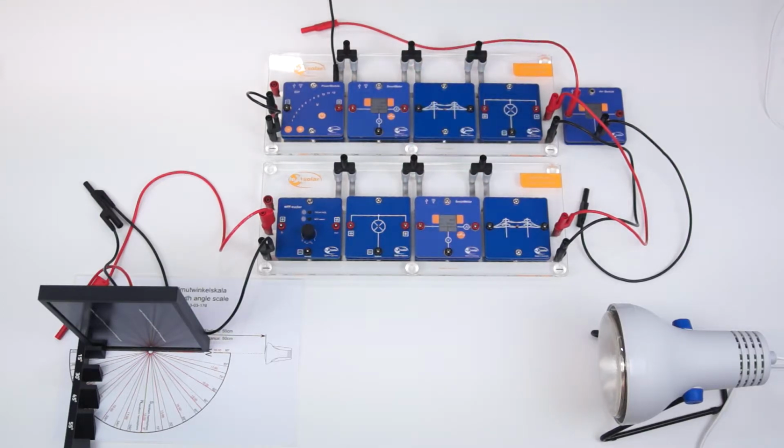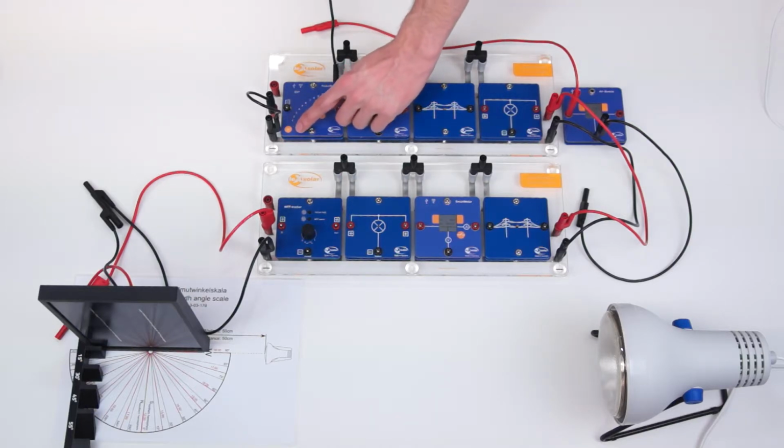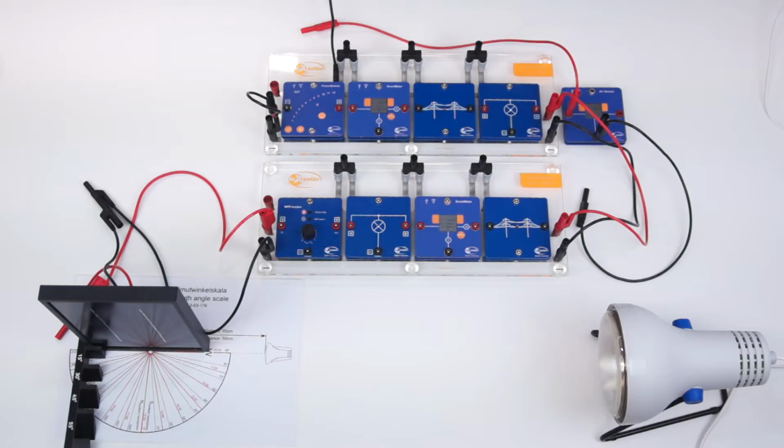To determine an overvoltage in a household in the experiment, we define a nominal voltage of 3 volts, and like in reality, it is only allowed to differ by 10%. In a previous experiment with the same structure without the photovoltaic system, it has already been determined that the voltage values are best observed with a transformer voltage of 3.5 volts at both households. In this respect, we maintain this voltage and turn on the power module.